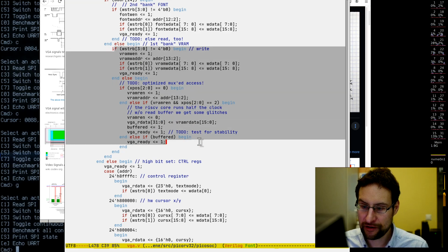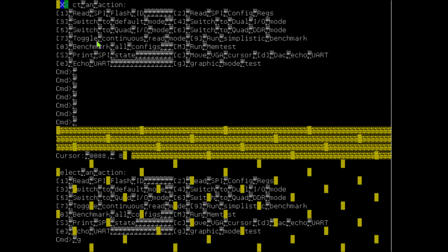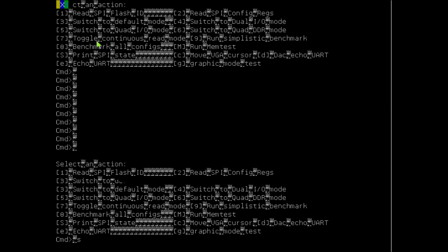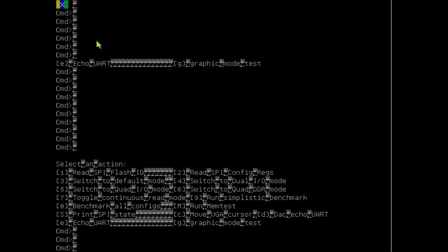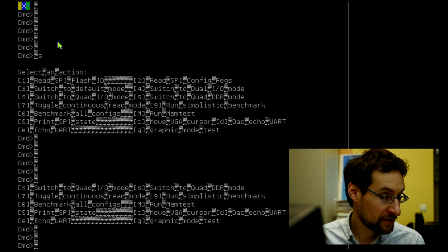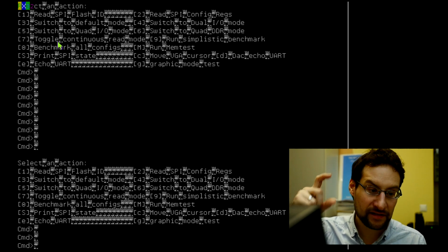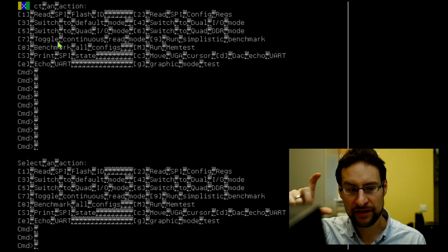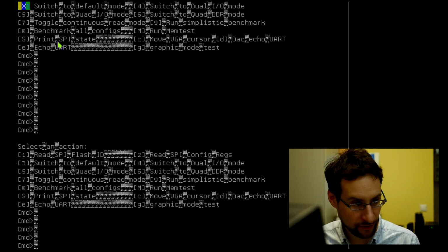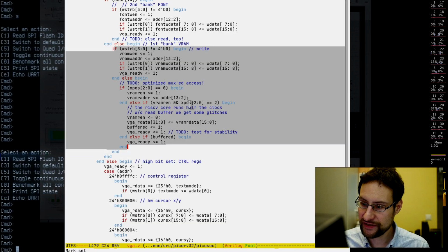The reason I have VRAM access is actually for scrolling. So this fancy scrolling here, we can toggle. My code has either scrolling or not scrolling, and I can toggle this with the press of S for scrolling. For the scrolling, we obviously need to read the VRAM back, and we only need this mostly for text mode scrolling. So this is why reading the VRAM for copying the data up there for scrolling is certainly quite nice to have, which is why I implemented that.